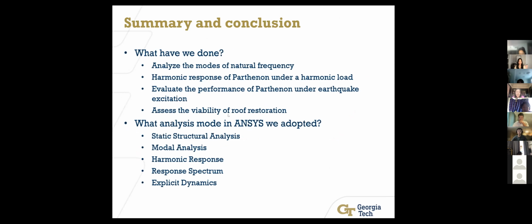So to summarize, in this project, a similar structure to the Parthenon in the Acropolis of Athens was modeled and analyzed with ANSYS. And we got outputs from 6 modes of natural frequency, evaluated the harmonic response, evaluated the performance of the Parthenon under earthquake excitation, and finally tested the viability of restoring the roof. And the analysis modes we used in ANSYS for what we did above are respectively static structural analysis, modal analysis, harmonic response, response spectrum, and explicit dynamics.